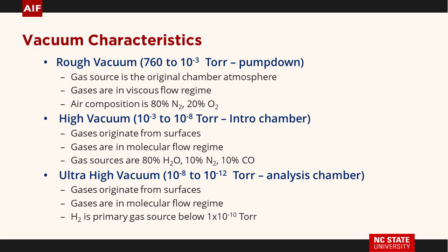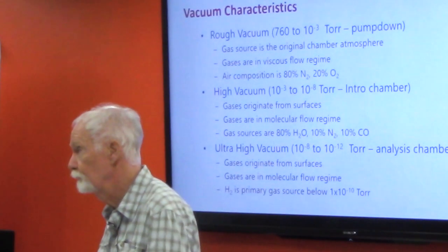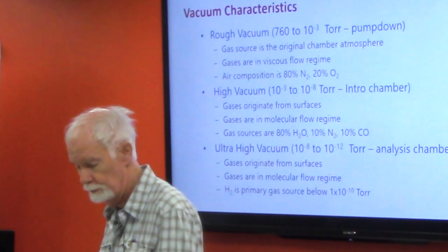And now your gases are water. Water is something we'll talk about a lot because if you have water in your system, it doesn't pump down very easily. Nitrogen, CO. Once you get to ultra-high vacuum, this may be a surprise: it's all hydrogen. So then it's all about your seals, how well you've made the connections.